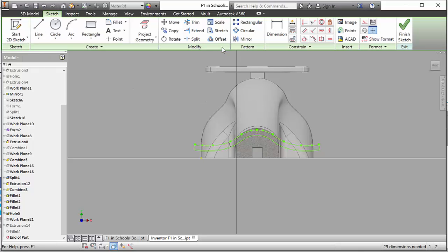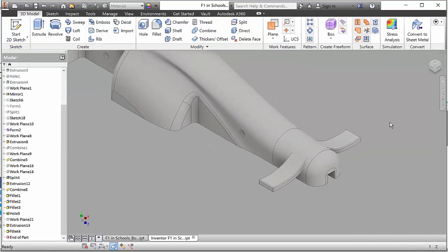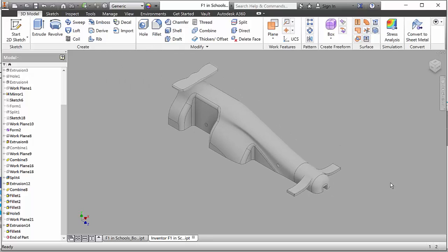It lets you create some more freeform type shapes. I offset the spline from top to bottom, added a short line in, and then mirrored that. Extruded that sketch and added some fillets to round off the corners. So with that spline command, you can create some interesting shapes.